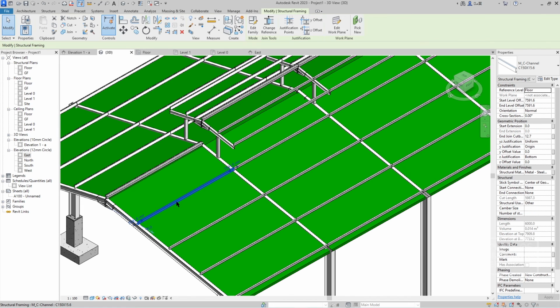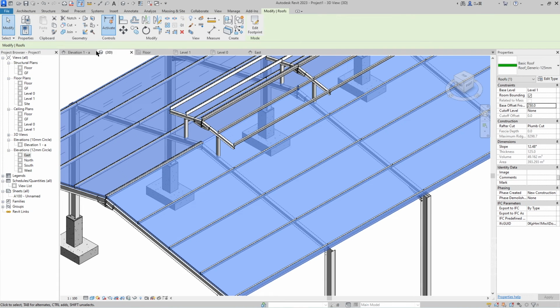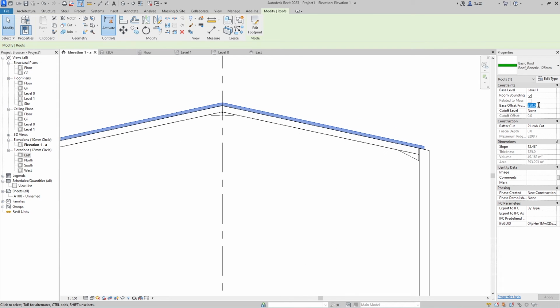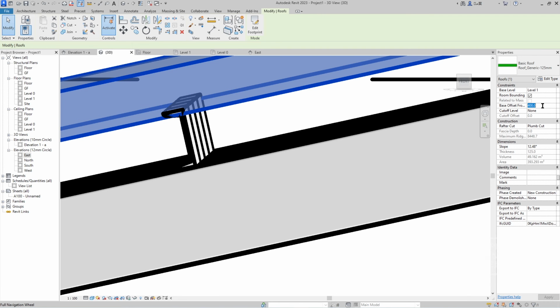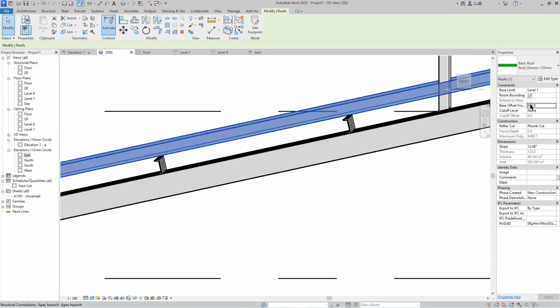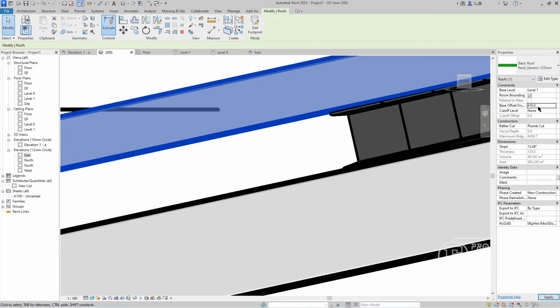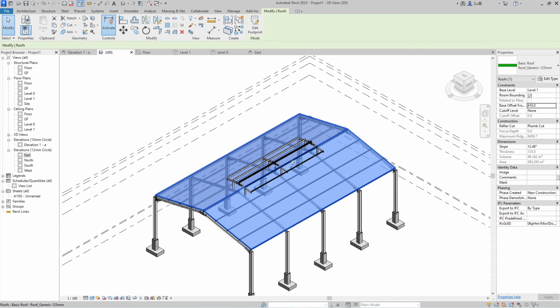All right, I have trouble here. All right, we Control Z first, and then this comes to level 1, the offset should be positive 115 maybe. We try to apply to the elevation view. Okay, maybe a little higher, good 400, a little bit higher again, maybe 500. Too high, so this one is too high, so maybe okay, this looks good. But the trouble here is that the center point is also included with the roof, but it's okay, we're going to edit it later.